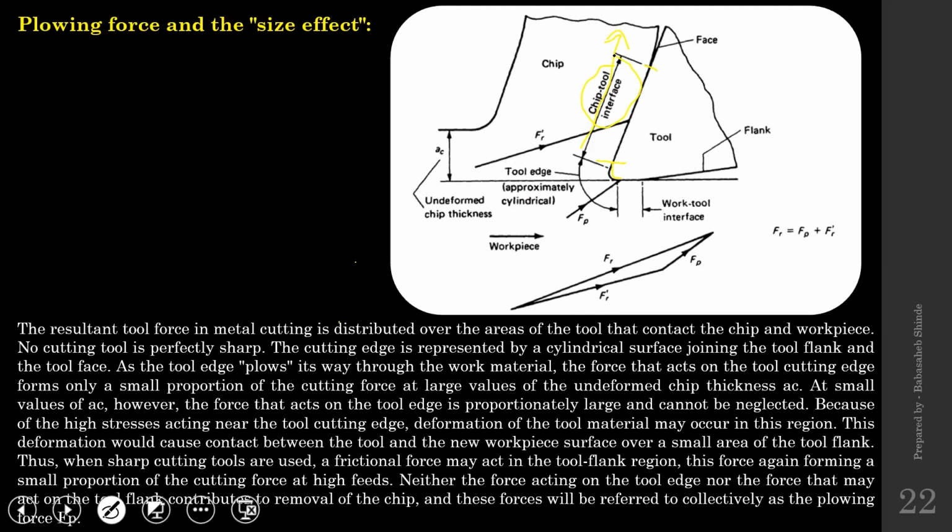And the third one, when the tool has got slightly worn out, there is a contact between the cutting tool surface and the finished work surface, and that zone is called the work tool interface. Now out of these three zones, the force acting on the cutting tool on the cutting edge where actual material removal takes place,